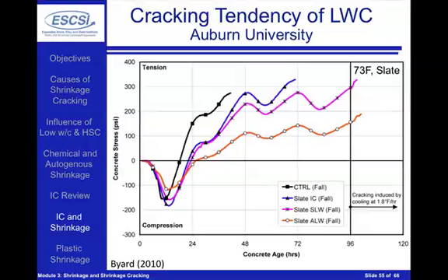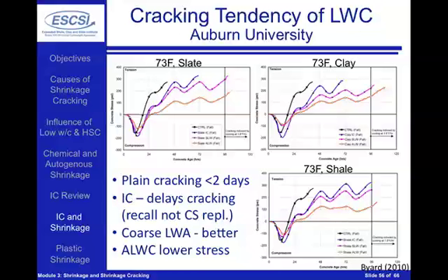If you're using an all lightweight concrete or a sand lightweight concrete, you can see the orange and the purple curves respectively that are again reducing more and more of the stress that's inside of the system. Again, it's important to note here that this internally cured concrete doesn't contain the full volume of water that would be needed to essentially replace all of the vapor-filled space caused by chemical shrinkage. And you can see here that this was done for many different types of aggregates, aggregates that were made by expanding clays, shales, and slates, and in all cases the internally cured concrete delays the age of cracking.